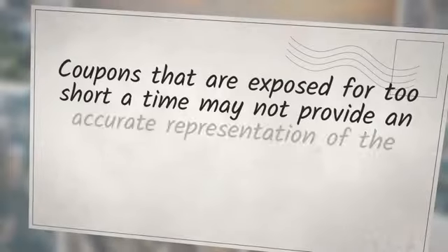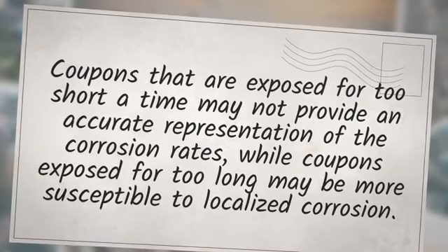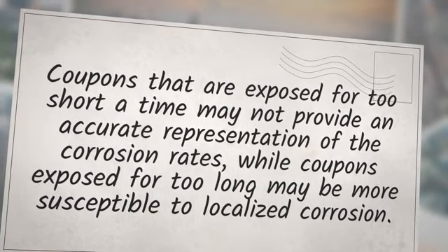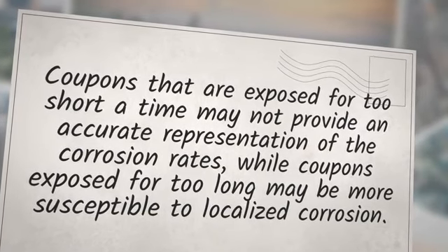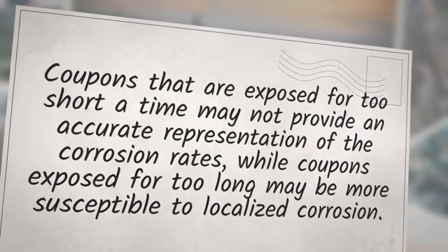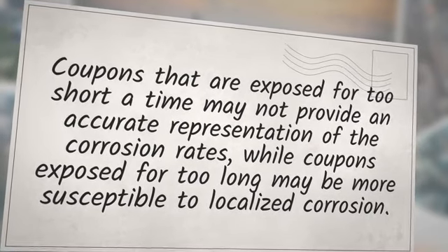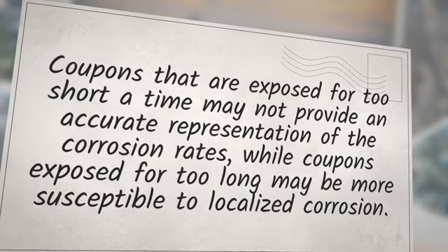Exposure time. The exposure time for the corrosion coupon should be chosen based on the expected corrosion rates and the frequency of monitoring. Coupons that are exposed for too short a time may not provide an accurate representation of the corrosion rates, while coupons exposed for too long may be more susceptible to localized corrosion.